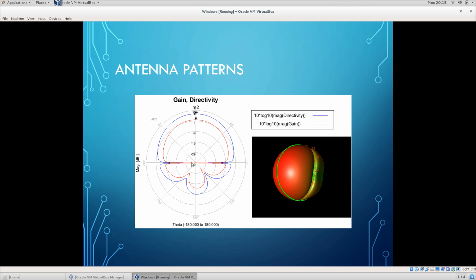So what we're interested in doing with antennas is making sure that the energy is directed in the way that we want it. This particular antenna is designed as a fairly low gain directional antenna, right? So it's directional, it has fairly low gain, but the energy is preferentially pushed in one particular direction. You can see this on the 3D pattern as well, where that's the back end, this is the front end, and this gap in the center is actually where the patch antenna board is, right? That's why you have this null right here, because it doesn't radiate very well end fire off of the edge of the PCB, right?